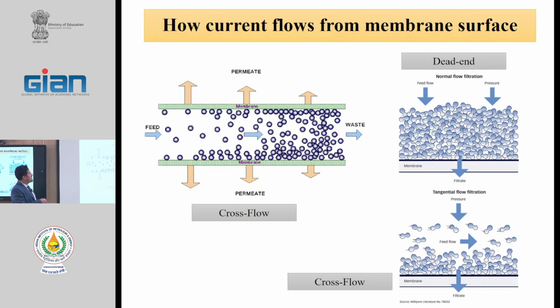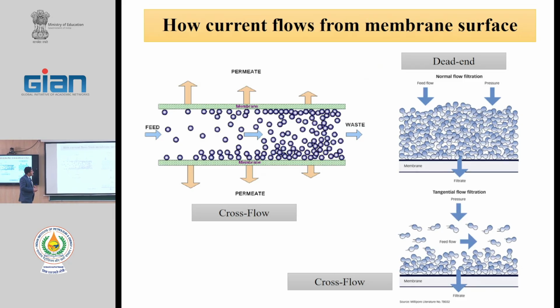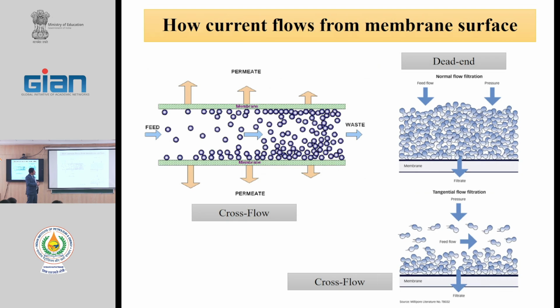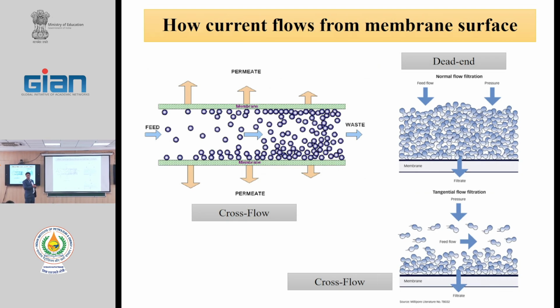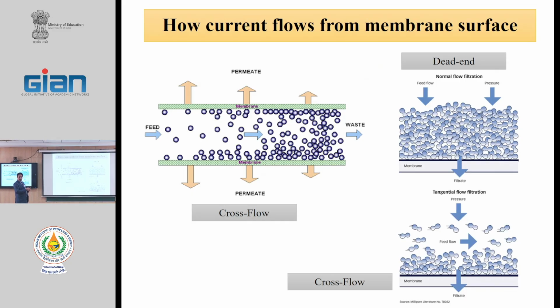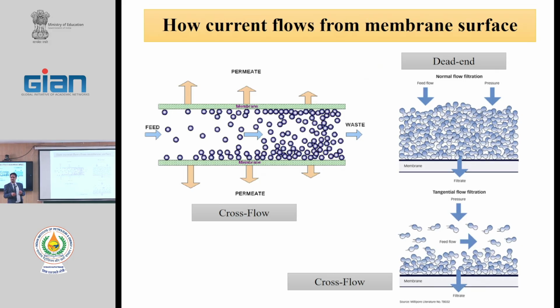that increases the membrane thickness. First, the solute should pass through this thick layer and next reach the main membrane. But in cross flow, the thickness of the concentration layer is low and the fouling is lower. Therefore, in cross flow, the fouling is lower than in the dead-end method.